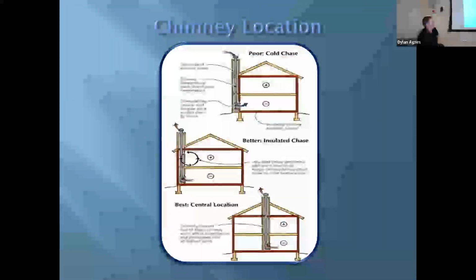If you go inside these older homes and use a thermal camera to take a picture of the inside of fireplaces, they're almost always blue. They're super cold. You can put a digital thermometer on the face of them, and they're just super cold. Trying to get warm air to go up that cold cabinet can be really difficult.